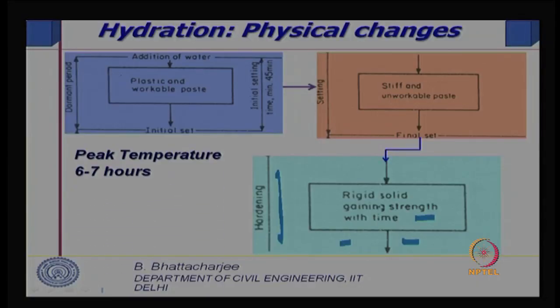Well, the peak of temperature occurs 6 to 7 hours after mixing the water, and the final set generally corresponds to about 10 hours or so, not more than 10 hours. Most of the codes will specify not more than 10 hours.